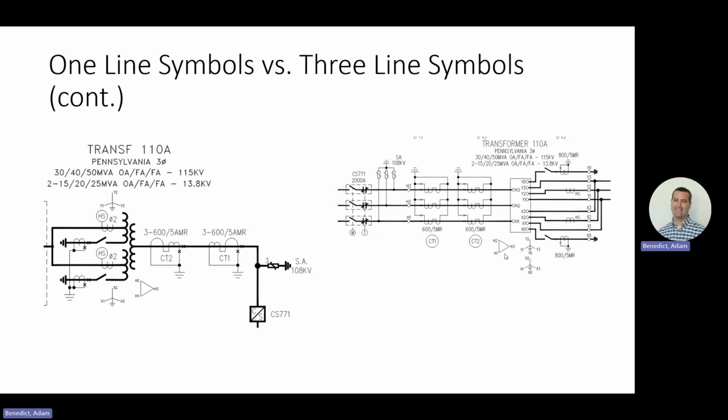Is X3 to Y3? Is that connection correct? Are my CTs shorted properly? Are my single phase equipment installed on the right phase? So that's why each one of these is done in a phase. So you get this done, and then you move on.